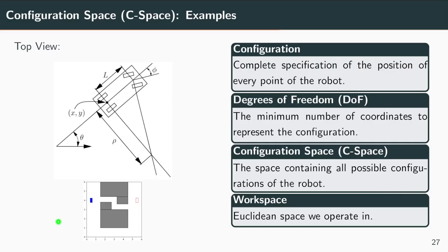Actually, the configuration space is 4-dimensional. I think you have x, y, theta, and phi also, because phi is important for the position of a point on the front axis or front axis wheels. So to encode that, you somehow also need that degree of freedom, right? So I think we have 4 degrees of freedom, and that translates down into the configuration space.